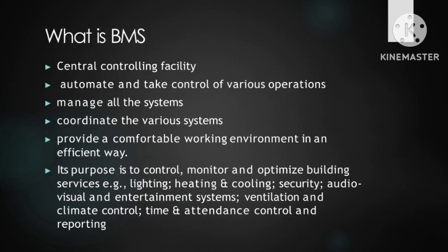Now, let's understand what exactly is a building management system. A building management system, or BMS, serves as a central controlling facility. It automates and takes control of various operations within a building. BMS manages all the systems and coordinates their functions seamlessly. Its primary objective is to provide a comfortable working environment in an efficient manner. Furthermore, BMS is designed to control, monitor, and optimize a wide range of building services.